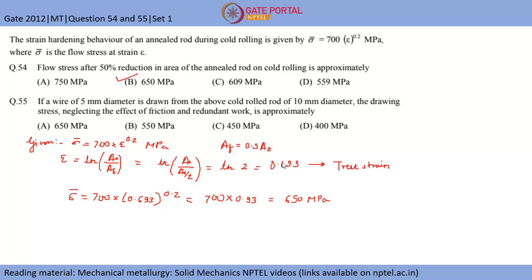Here the same thing is there, we just have to find out the drawing stress. If you know the equation of drawing stress, like how you evaluate that, you will be able to tell the answer. You have to follow a similar procedure. First find out the true strain, then the true stress, and from both this true stress and true strain, you need to evaluate the drawing stress. And you have to neglect the effect of friction and redundant work, which is there in the deformation process.